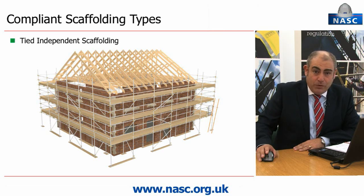Bay sizes up to 2.4 metres. Note there is no 2.7 metre bay size included. We see the welcome return of single bay facade bracing without the need for additional plan bracing. Lift heights commonly up to 2.1 metres, but also accommodating floor height lifts up to 3 metres. Safe heights from the operational guide up to 16 metres, or scaffolds up to 50 metres from the eGuide.